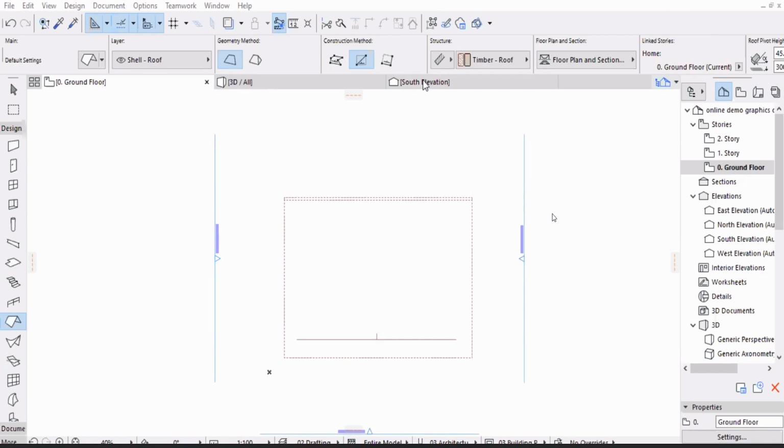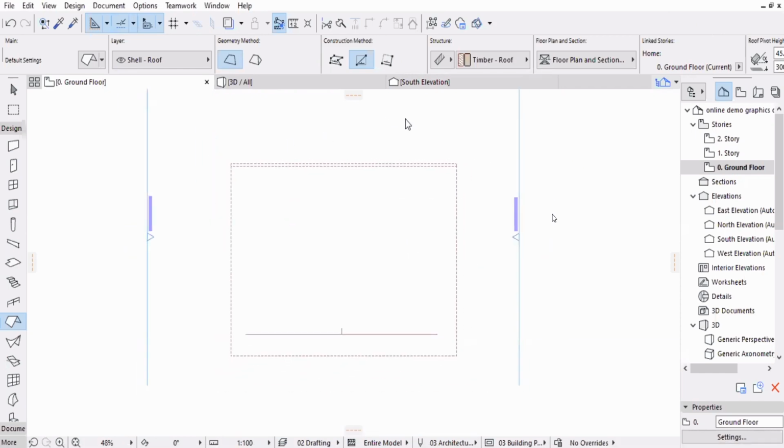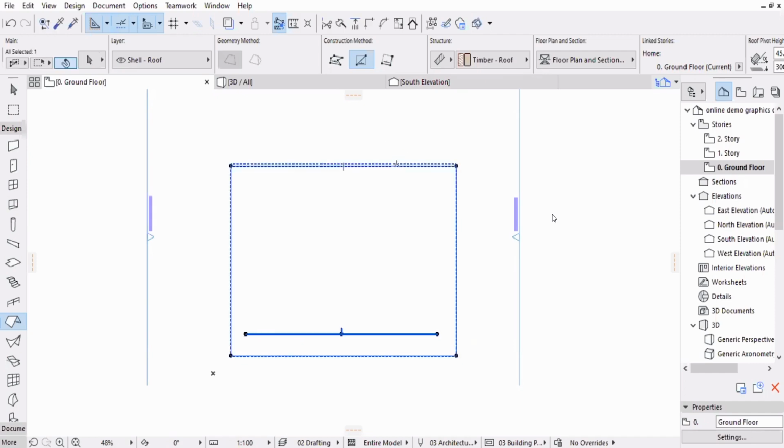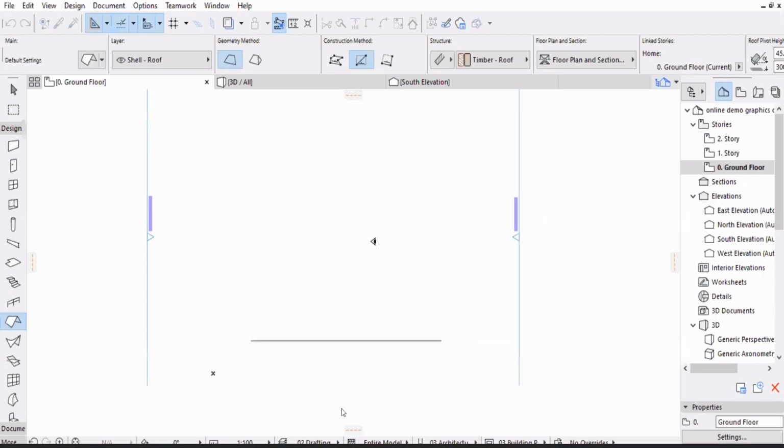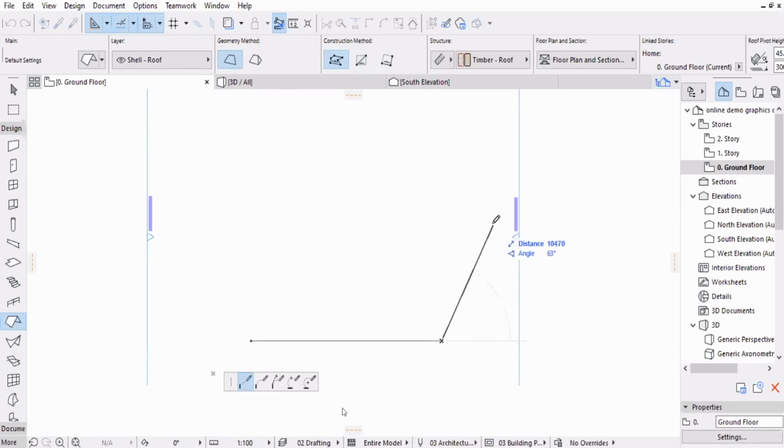All right. So this is the roof, and if you want to draw, let's say, another roof which has a different shape, which is not square, which is a polygonal thing, then the steps are the same. I may just delete this and do the same thing again. We'll just draw the pivot line. And this time we'll use the polygonal, and we'll use it from this point so that we are precise.